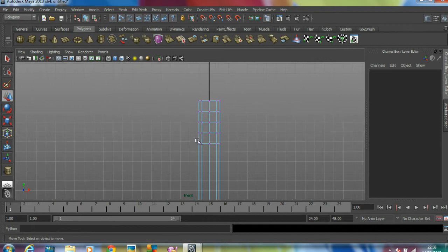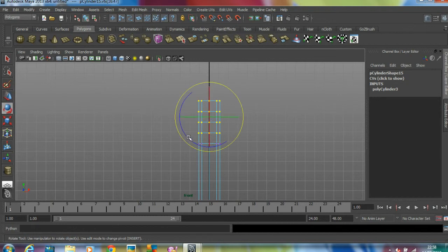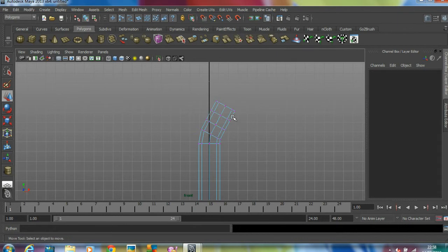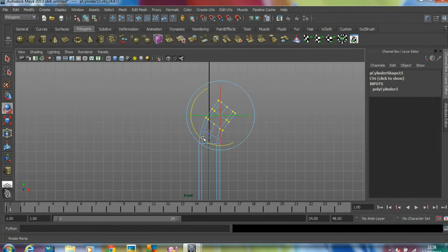So just leave one, so select the top four, use rotation, little bit of rotation, move it. Select all these points, if you hold Control Shift, you can add the selection, little bit turn, move it. If you hold Control, you can deselect these points, rotation, little bit rotation, deselect these points, and this one back to normal.